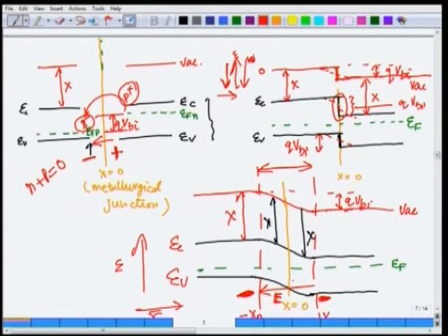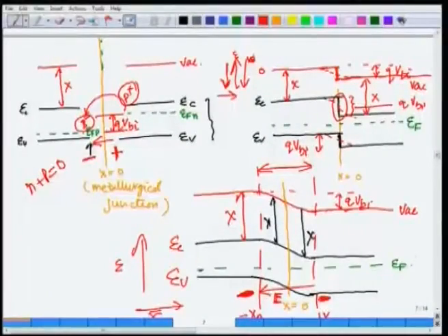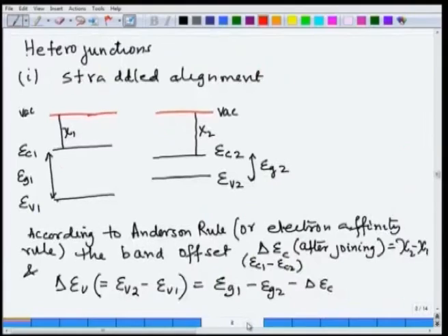Since you will be learning about p-n junction a lot more, I thought I would tell you about the band diagram right now, and later when the device is done, this whole story will be repeated. At that point this band diagram will be immediately drawn, but we will do it quantitatively and derive all these curvatures, by how much amount they will fall down, what the built-in voltage is, etc. That will be carefully calculated, and you will have another opportunity to learn. But let us now move on to heterostructure, which we may not cover in that much detail later.